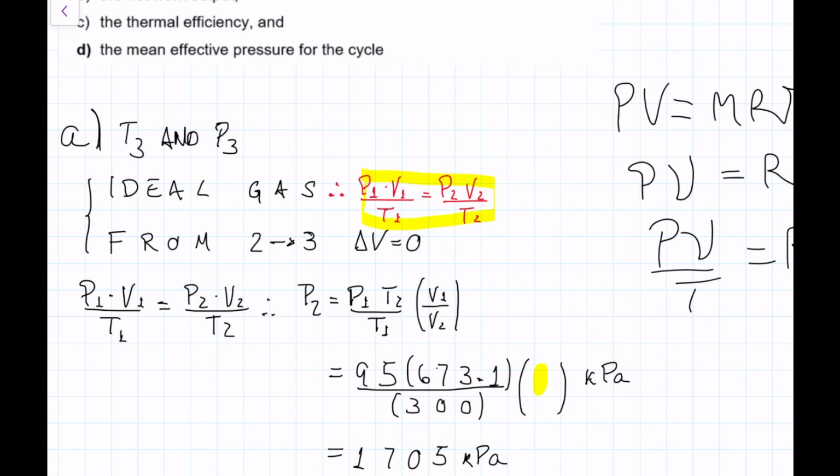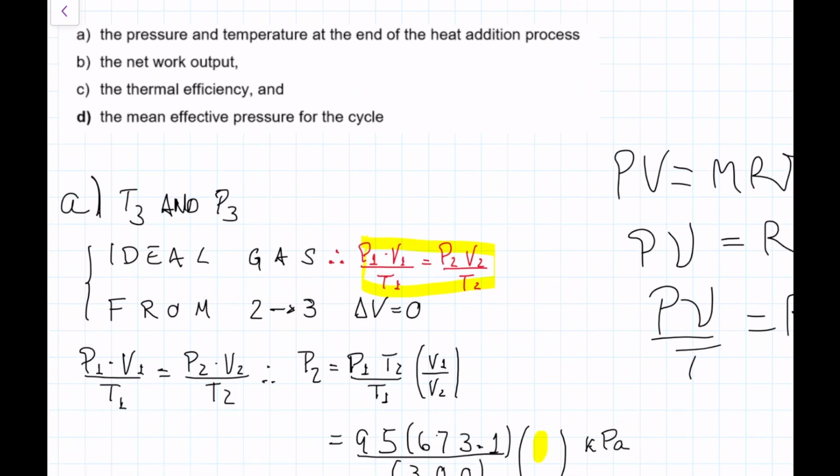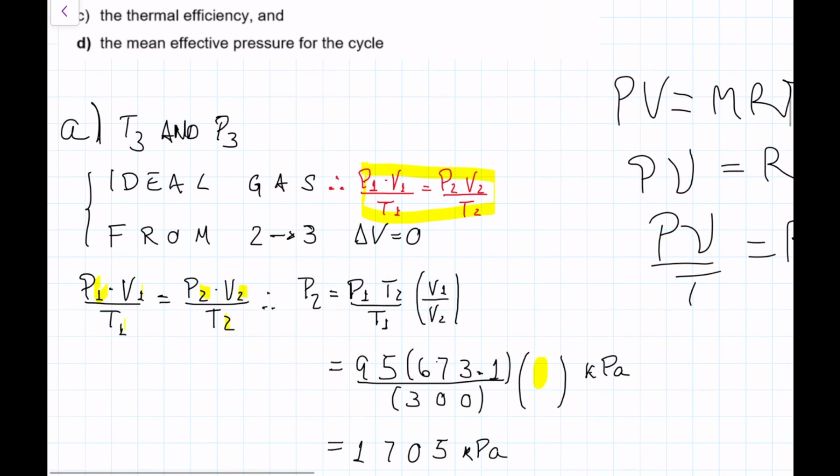All right, first thing I want to do is find what is my P2, right? So for now I only have my T2, 773, that we grabbed before by interpolation. But my P2 I still don't have, I don't know the pressure 2. Okay, so I'm going to use PV equals nRT, and I'm going to use it for state 1 and state 2. And you'll notice that we have everything we need. We have the pressure 1, that's 95 kilopascals. We found the temperature 2 from the interpolation. We had the temperature 1 since the start. What we don't have is volume 1 and volume 2.